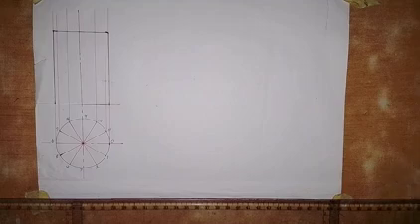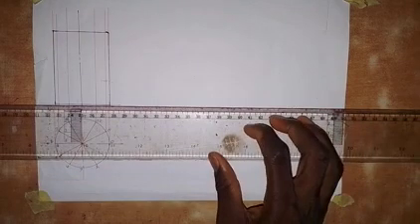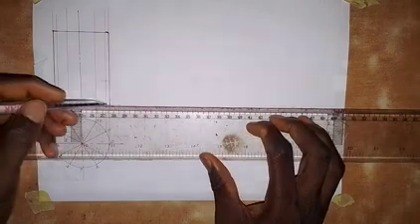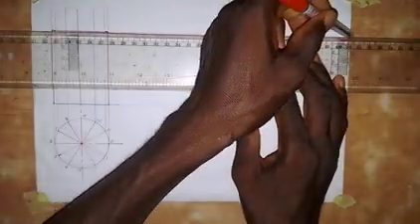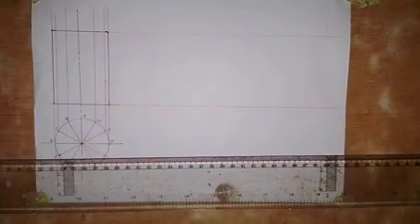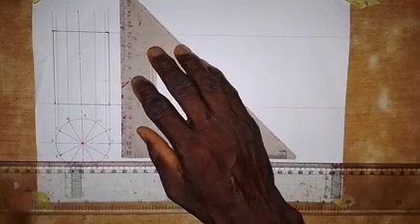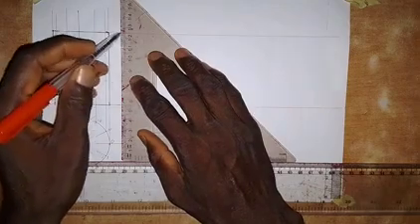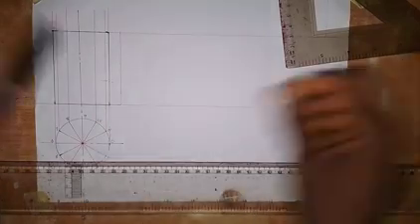Now let's go for the surface development. We are cutting it from this line, that is from point 6. What we have to do now is to draw a horizontal line, come onto this base, and then draw a horizontal line to this side. Then come up here also and draw a horizontal line to this side. Alright, so we are cutting it from point 6. Now move away a little bit from the given view and draw a vertical line here like this. So this point here is point 6.